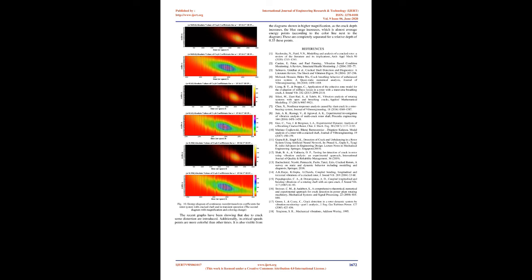However, for the transient signal of the single shaft in the desired rotor system, the continuous wavelet transform with the Morlet mother function is used and the results are shown in the form of energy diagrams of the wavelet coefficients in Fig 10. To have a more clear observation, the magnified graph of the coefficient's energy is plotted along with the coloring change.